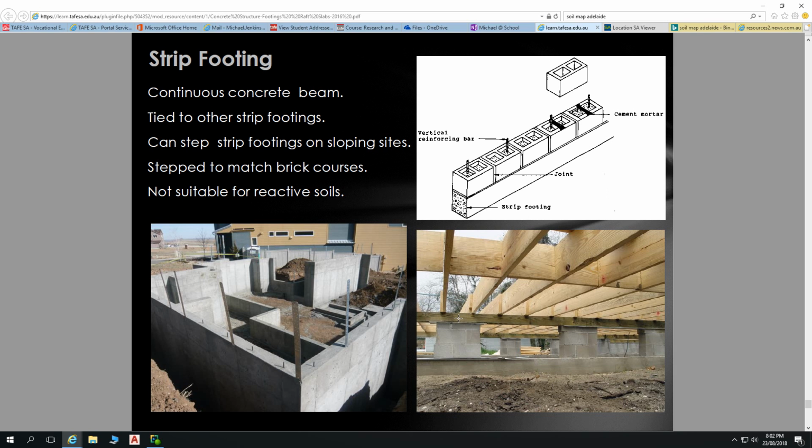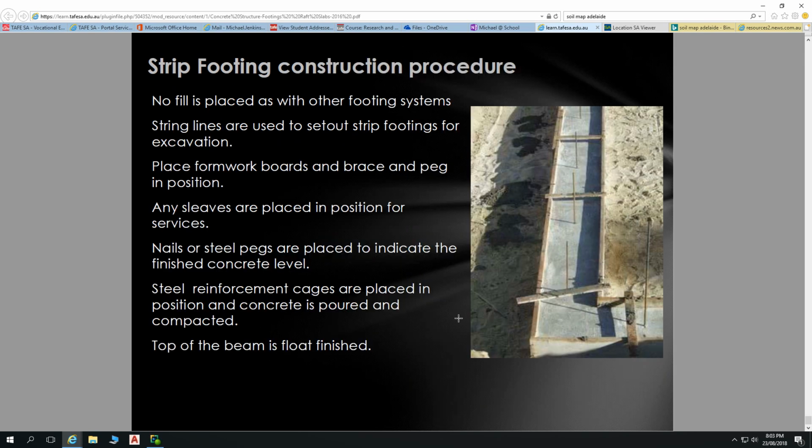You'll see it for verandas. So verandas that are built out to carry a concrete slab on the veranda, that'll be core filled concrete block. I did it with a shed in a sloping site, cut away, but then concrete blocks, core filled, concrete slab on top of that as well. Same sort of, yeah, it's a good approach for any sort of suspended slab like that. So that's our concrete footings.